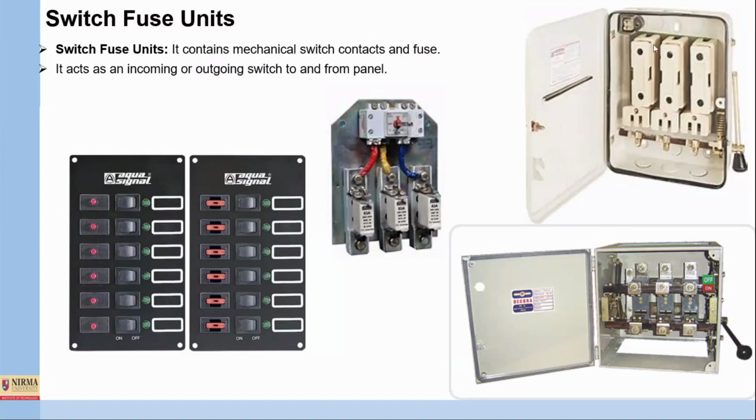So for that, instead of using normal molten fuses, you will use these cartridge fuses. These are the cartridge fuses. Instantly, when the fuse blows off inside, you simply replace this cartridge and connect a fresh fuse cartridge. So this is the panel now. In place of this, we are using three-phase cartridge type fuses, and here the fuse has been loaded.